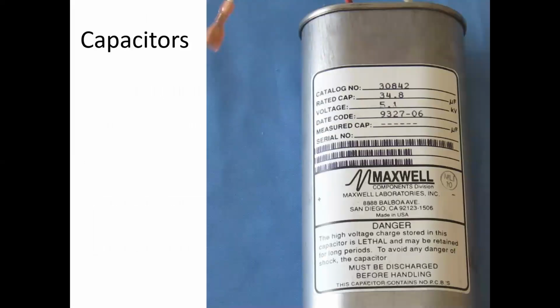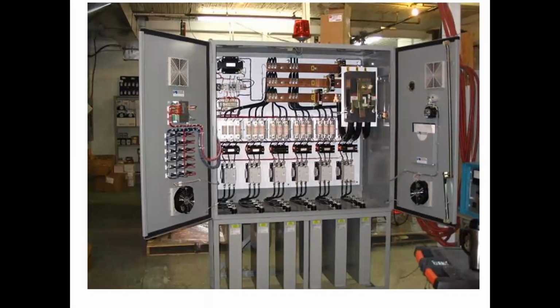So what do we do? We add capacitors. Here's a capacitor. There's a whole bunch of capacitors. And with power factor correction, we need to be able to adjust how many capacitors are online at any given time, because we know that the electrical load inside the facility will vary. It's never going to be a static 100 amps. Lights are going to turn on and off, motors are going to turn on and off, and because of that, the reactive component of current will get higher and lower. And so for active power factor correction, you need to have multiple arrangements of contactors with groupings of capacitors, and those contactors engaging and disengaging depending on what the power factor is on the line.